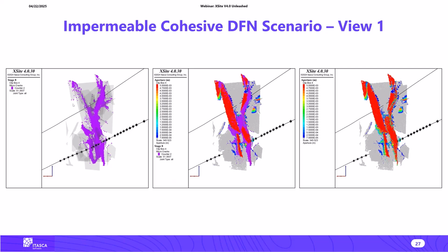This plot on the left side shows only induced micro cracks, but you can see how those micro cracks relate to pre-existing joints, which are shown in this slide as transparent polygonal surfaces. You can see that the fracture propagates, gets diverted into a pre-existing joint, and then reinitializes from the edges of that joint.